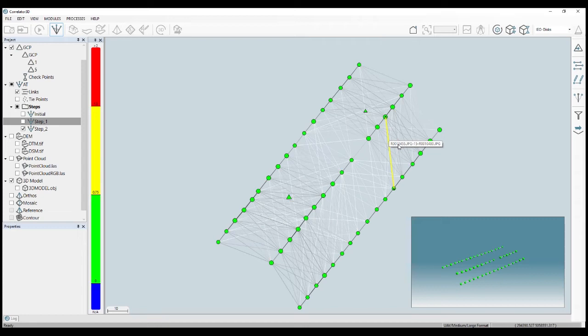And I suggest that, even if you run a project using the automated workflow or you do something automatically, always review the aerial triangulation report. Very, very important. That's where everything is happening. If you don't have a good bundle adjustment, a good aerial triangulation, you might have problems later in the processing, and that's where all the accuracy will be defined. So be sure to review your AT report and validate the residual of your ground control points.